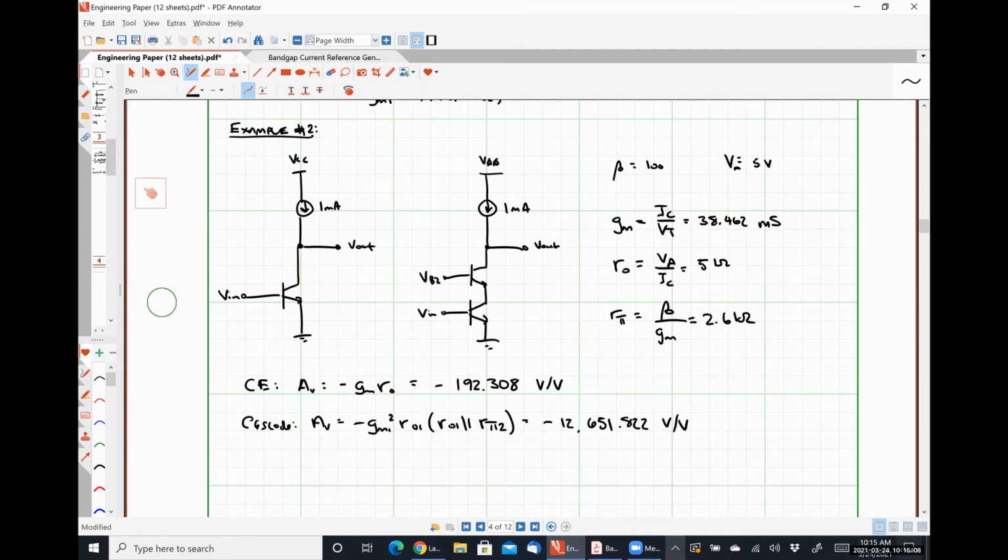Yeah, we're going to use another BJT, but we're going to use a PNP BJT to do it. So my question to you guys is then, should we represent our practical current source with a single BJT or a cascoded BJT current source? Cascoded, why cascoded? Or do you have any idea other than? So it does have something to do with the degeneration, but let's look at this example just real quick, right?